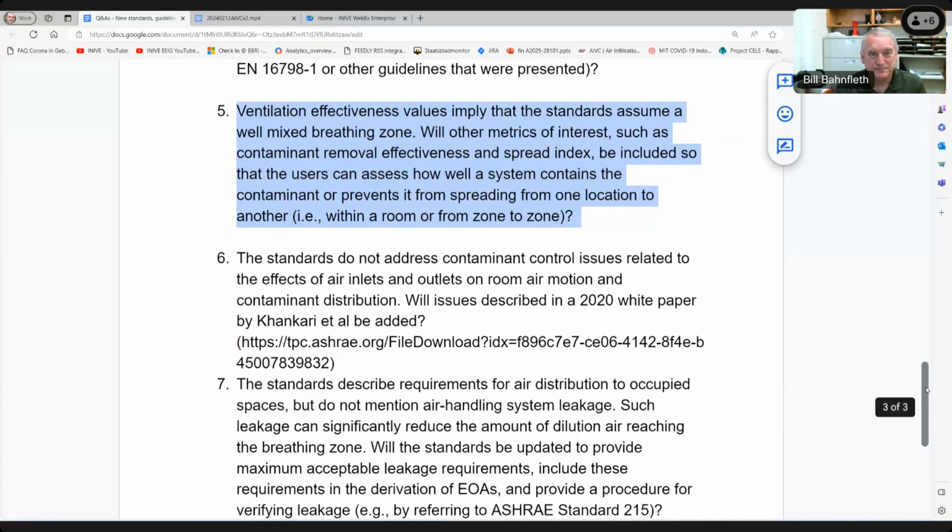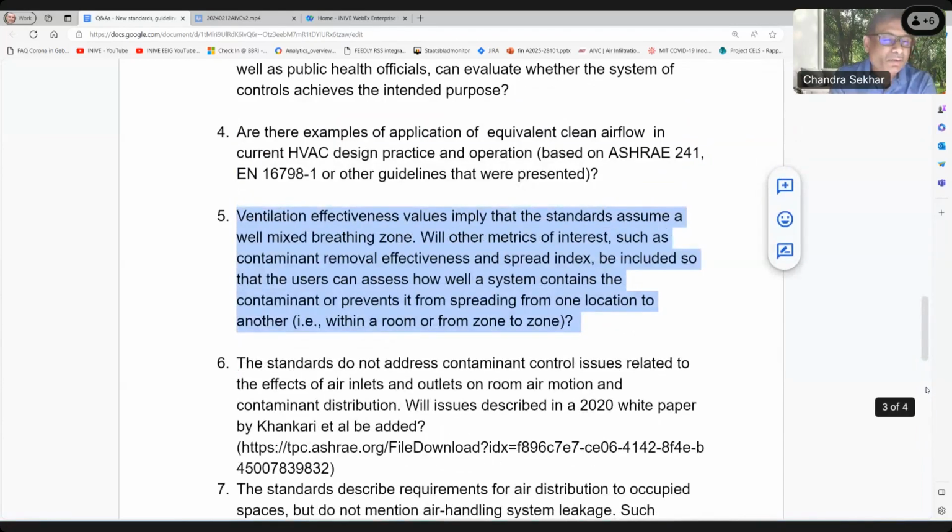Okay. Also, if I may add in here, Peter, the whole question of air distribution and its impact on how we could address the exposure control in terms of what the person is exposed to. Therein comes your personalized ventilation, local source control, exhaust. All these are important considerations which we're not quite there yet, as Bill has just described, but I'm sure certainly the effort will be there to incorporate some of the scientifically established research findings into practical application moving forward.